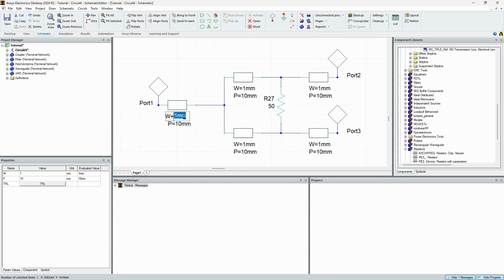Now we got to change our values, with these transmission lines here being the same width and length, and we calculated those to be 0.311. Don't forget your units. And then here, this is going to be the predetermined value of 3 millimeters. So we're going to go through and change these. There we go. And so now same for here with the final calculation we did.